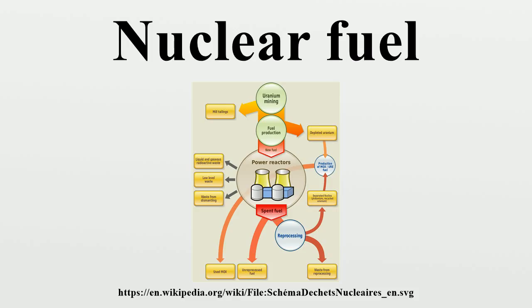Liquid fuels. Liquid fuels are liquids containing dissolved nuclear fuel and have been shown to offer numerous operational advantages compared to traditional solid fuel approaches. Liquid fuel reactors offer significant safety advantages due to their inherently stable, self-adjusting reactor dynamics. This provides two major benefits: virtually eliminating the possibility of a runaway reactor meltdown, and providing an automatic load-following capability which is well suited to electricity generation and high-temperature industrial heat applications.